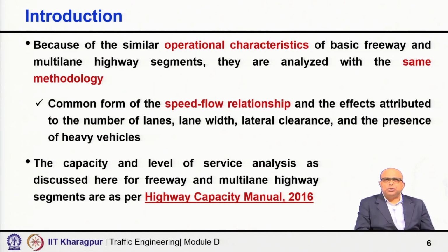Because of the similar operational characteristics of basic freeway and multi-lane highway segments, yes, they are different facilities, but they have similar operational characteristics, and therefore the same methodology is applied for capacity and level of service analysis. Methodology and approach is the same. When I say similar operational characteristics, I mean a common form of speed-flow relationship.